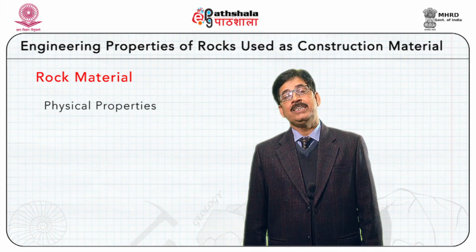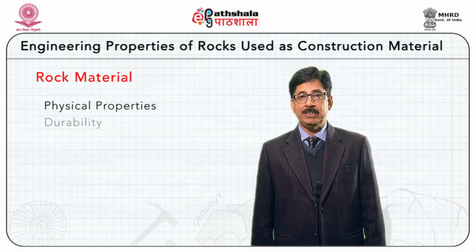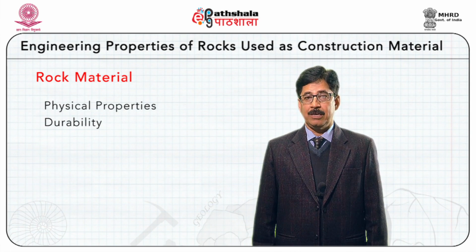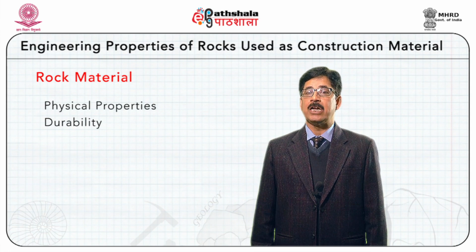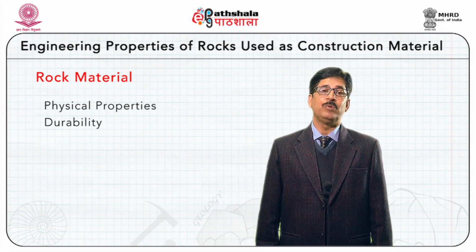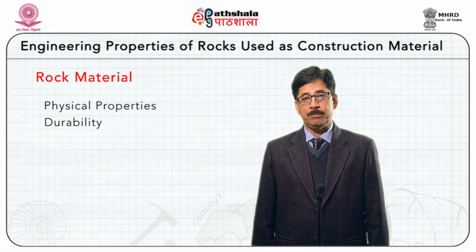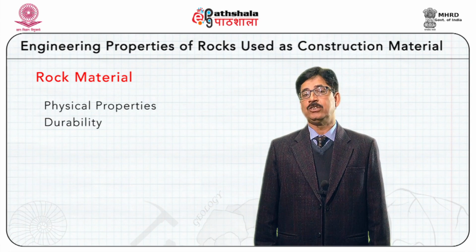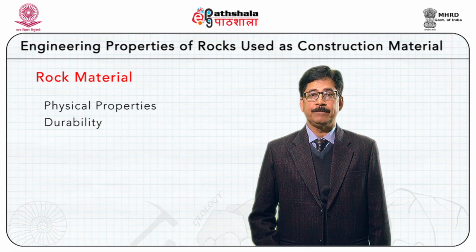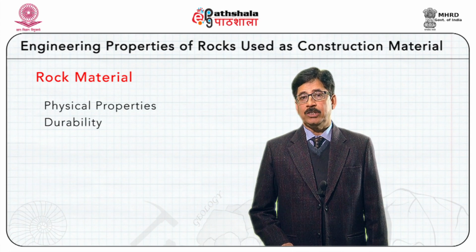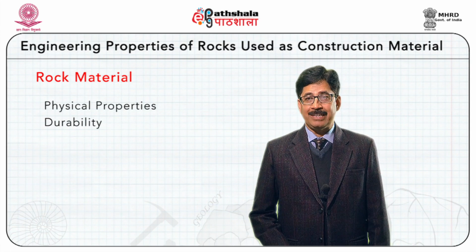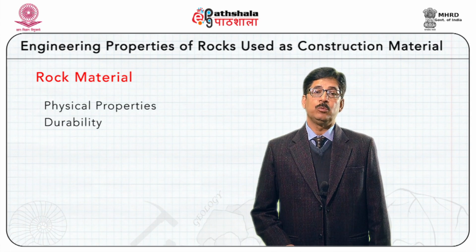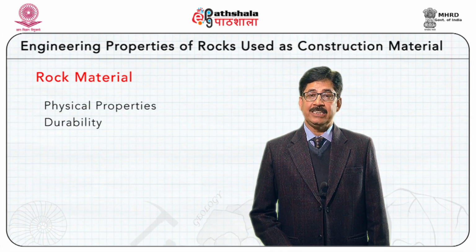When we are using rock material for construction, we have to ensure its durability. Durability is defined as resistance to natural deterioration of rocks, because all our structures are exposed to the atmosphere, so they will be subjected to the vagaries of weathering, and hence durability is important. We can use a test to assess the rock's durability, and that test is known as the slake durability test. Nowadays, because of atmospheric pollution in urban areas, we have a lot of acidic rain, so we have to ensure that we are not going to use those rocks which can easily be dissolved in an acidic environment.